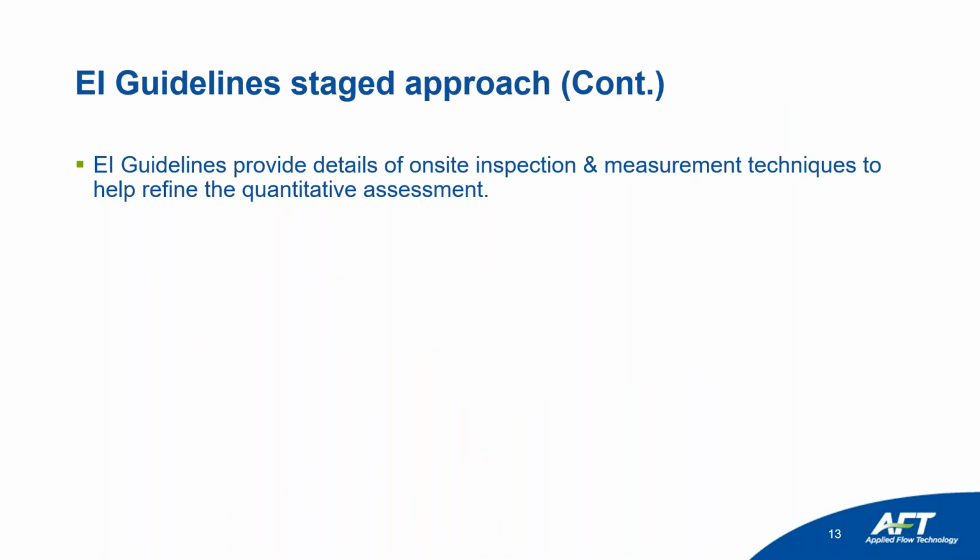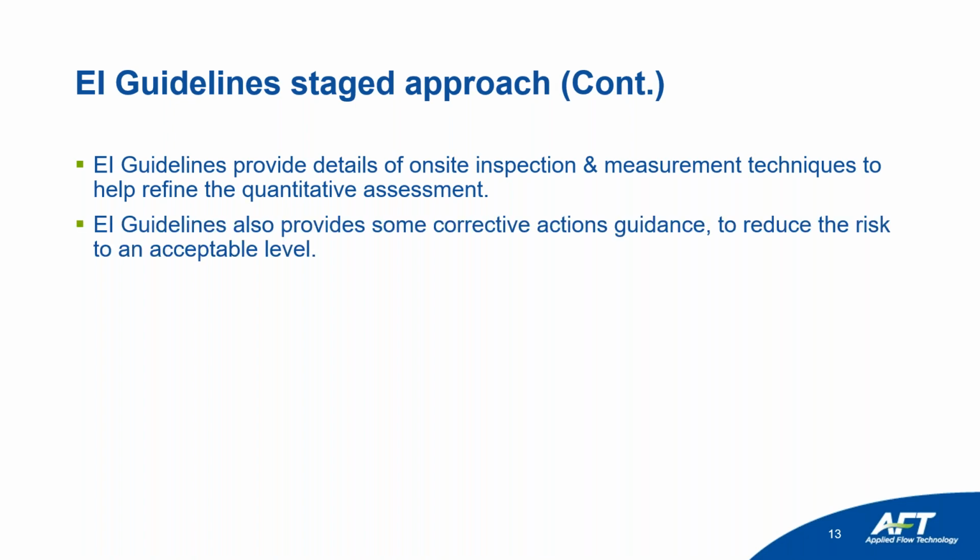Then when you have the LOF, the Energy Institute guidelines provide details of on-site inspection and measurement techniques to help you refine the quantitative assessment you have just done. And finally, the Energy Institute guidelines also provide some corrective action guidance to reduce the risk to an acceptable level.